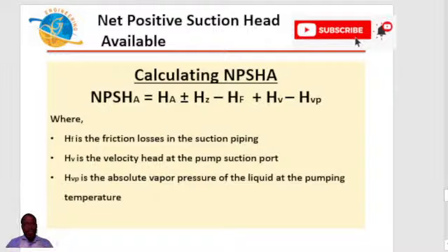So when they supply the mechanical data sheet, which contains some of the mechanical features of that particular equipment, one of the things that you need to check is the margin between your NPSHA and the NPSHR. Don't forget I said your NPSHA must exceed your NPSHR. So usually, at least that difference has to be at least 0.6 meter. In your own project or in your company, you might specify, depending on the project, say 0.8 meter. All this is just to do what? To prevent cavitation from occurring in your pump.